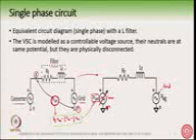Now the point N here and the point N here, note this very carefully, these 2 points are at the same potential. The point N here is the converter neutral and the right hand side N is the grid neutral. They are at the same potential, but they are not physically connected.